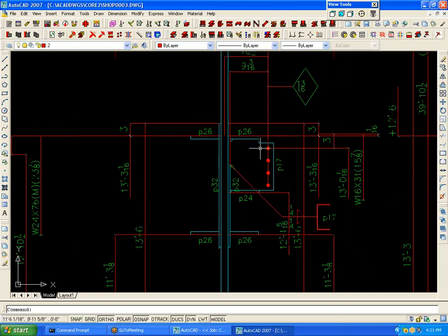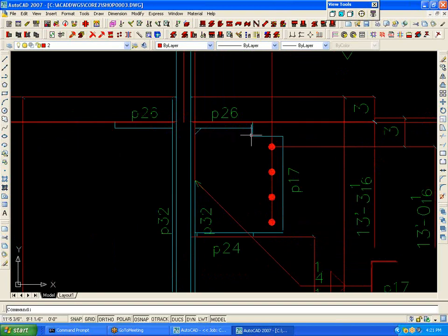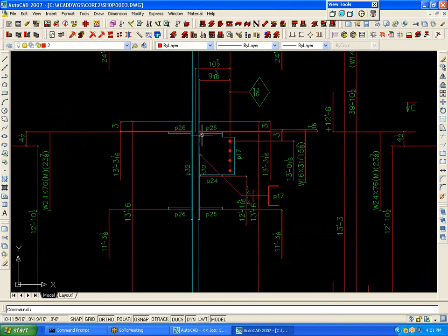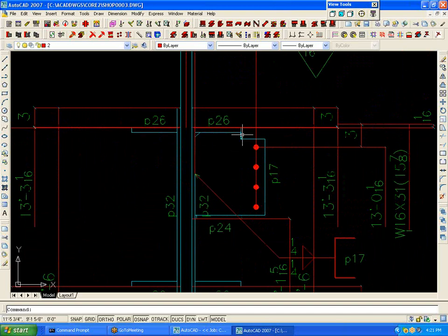Since we eliminated that half-inch stabilizer plate, the system automatically took the shear plate and extended it up and welded it and put a little clip on the corner to clear the fillet weld and welds it underneath the continuity plate. You didn't have to think about that. It was automatic. Now, this connection was written with the web, but these doubler plates were written with the moment flange connection.